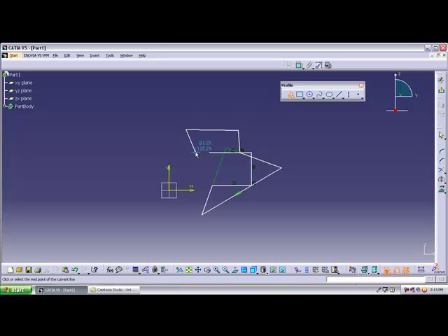But in these conditions, some more problems will happen. If you want to draw a straight line, it doesn't come out straight. For this, you should release the Shift button, and then you can get an exactly straight line. So when you don't want to disturb other constraints while drawing the profile, you should hold the Shift button, and then you don't get any constraints.